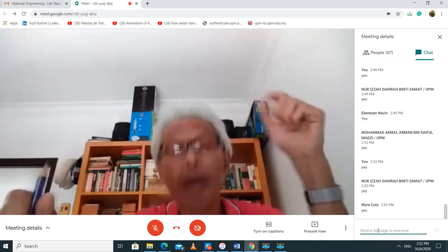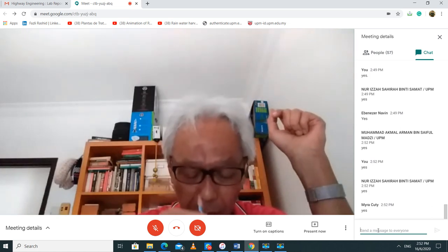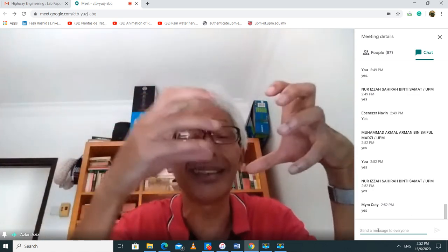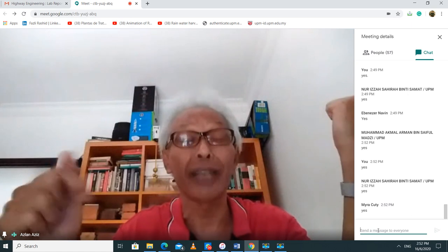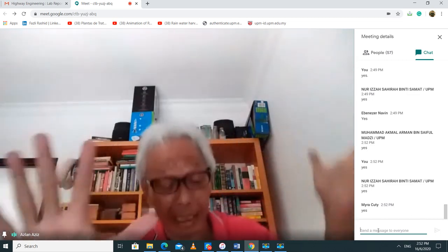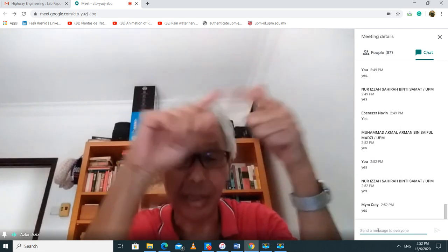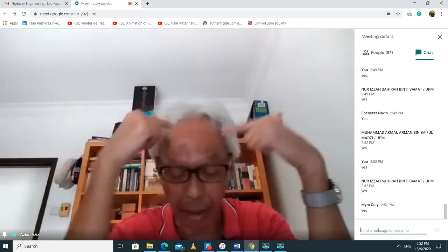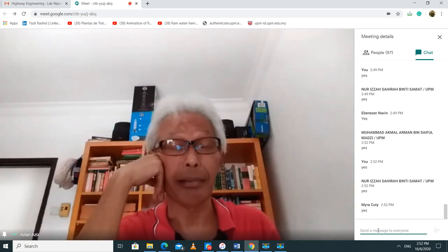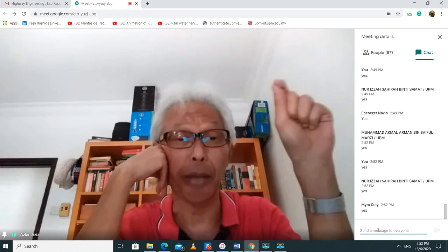Okay. Now, you also see in that equation, you find the shear stress, you have C and you have sigma tangent phi. That combination of the vertical and horizontal stresses also goes into the equation. Okay, guys? So, reminding you about all of that. Now, you have the peak of the Mohr circle. You have the sigma 1 and sigma 3. Now, I want to draw the stress path as what the note says. It says locus of peak of Mohr circle, the top of the Mohr circle.